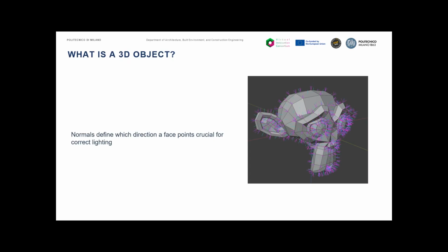Regardless of how well the materials and lighting are set up, you will not see it if the normals are flipped. Flipped normals are among the most common artifacts when importing geometry from, let's say, CAD systems or photogrammetric reconstruction pipelines. Recognizing them is very important, and fixing them is a lifesaver and a basic diagnostic skill that will help you a lot later.